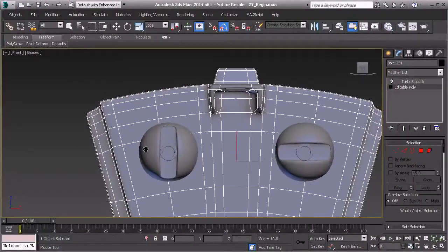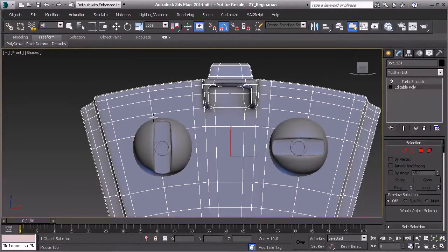So if I zoom out here, I'm going to draw the inner circle first this time. So I'm just going to left click and draw that out. Okay, and I'm just using a mouse here. And then I'm going to left click and hold the outer circle. Draw that out, and then we're going to left click and drag those lines through that topology, and notice it'll just create those polygons.